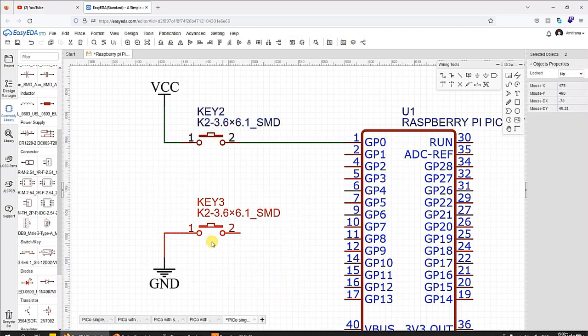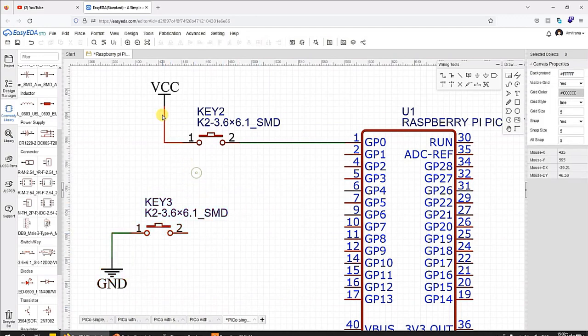In a microcontroller system, if you are not giving logic 1, it doesn't mean that the pin is getting logic 0. And if you don't ensure that externally, then your pin may go into a floating state or a high impedance state where you cannot understand what is exactly going on this pin, which may lead the system to malfunction.